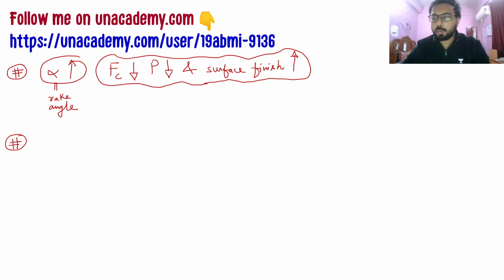I want you to remember this in as few words as possible, because again, don't just remember the whole theory, just remember the thing that is coming out of that theory, and that information I am writing here. So rake angle increases, these two things will decrease and surface finish will increase.